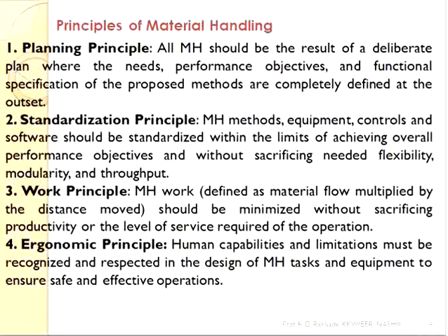Then there are various principles of material handling, such as the planning principle. All material handling should be the result of a deliberate plan where the need, performance objective, and functional specification of the proposed method are completely defined at the outset. Second principle, that is the standardization principle. Material handling methods, equipment, controls, and software should be standardized within the limit of achieving overall performance objectives and without sacrificing needed flexibility, modularity, and throughput.